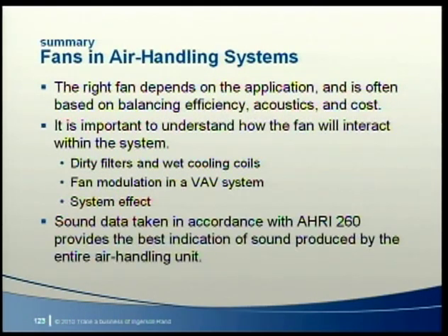Dave explained the importance of quality sound data and the impact of the air handling unit on fan sound. Finally, most problems associated with low airflow or noisy operation can usually be avoided through proper fan selection, better duct design, and fan installation, or a little more thought about how the fan will operate as part of the system.